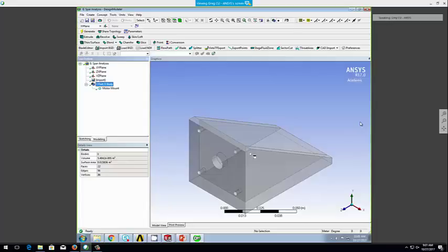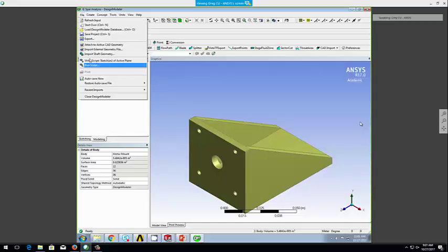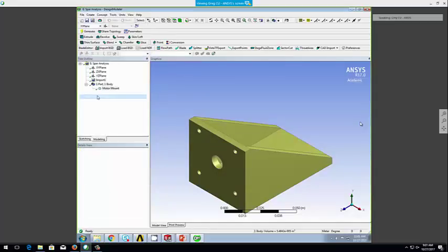I can change the magnification factor here, right? So this is at maximum. We've got a displacement of 4.6591 times 10 to the minus first inches. Look at equivalent stress. We're well below the equivalent stress.